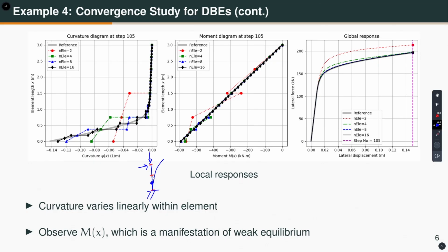So, this circle is integration points. I have 3 integration points for the bottom element, and then for the top element which I am drawing here, I have again the 3 integration points, right. So, these 2 integration points for the 2 elements case are at the same location, right. So, I am recording their bending moment at the section level, and you see for the top one it is here, for the bottom one it is here.